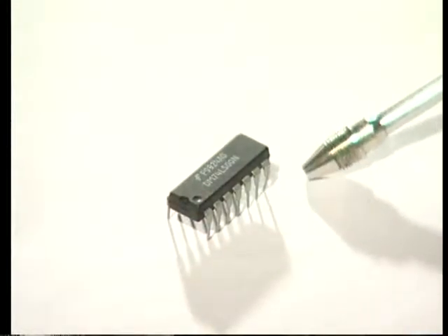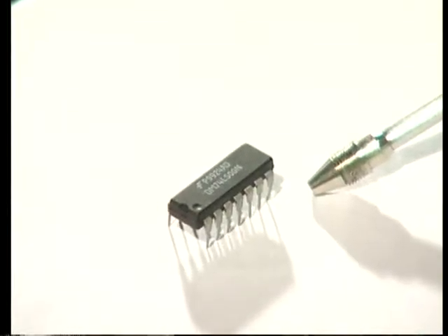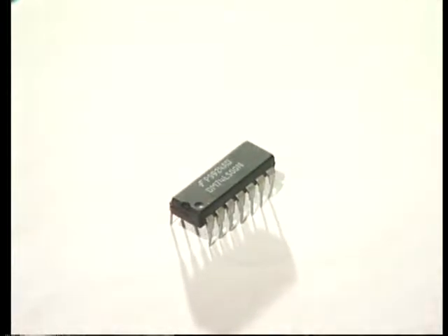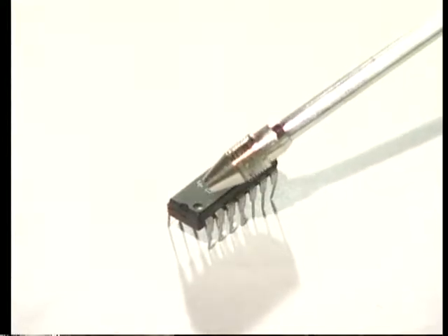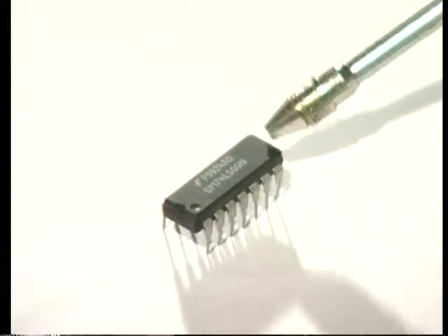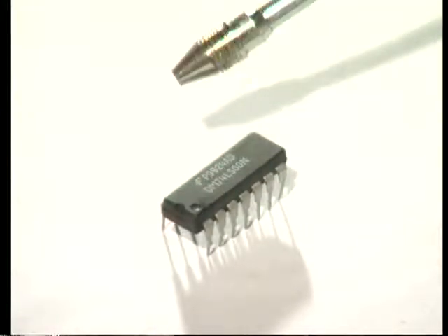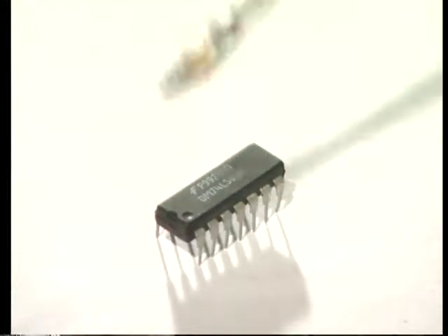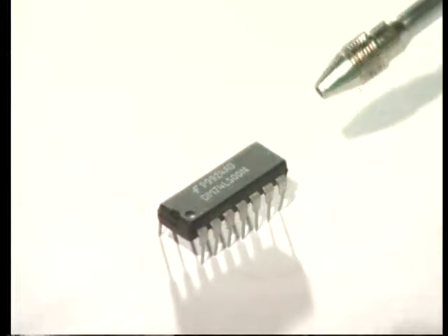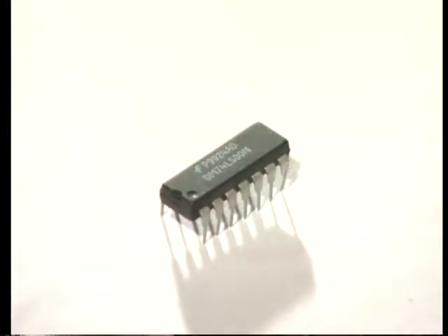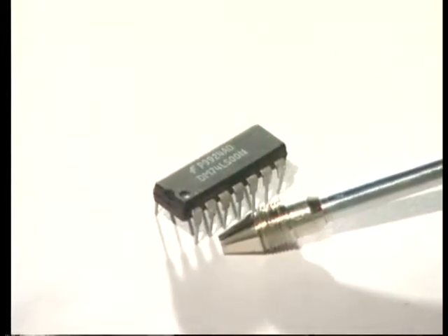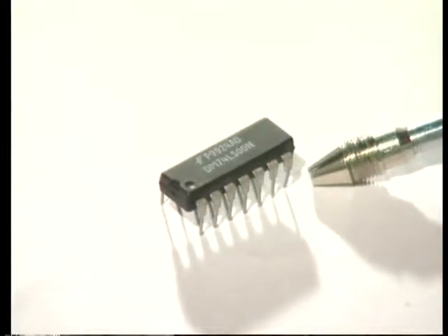Here this is the 7400 quad 2 input NAND gate. You can observe a notch at one side, the second side is flat, there is a cut in the first side. So, keeping the cut to the top and viewing from the left, the top pin is pin number 1. So, we come from pin number 1, 2, 3 as such up to pin number 7, which is the ground.